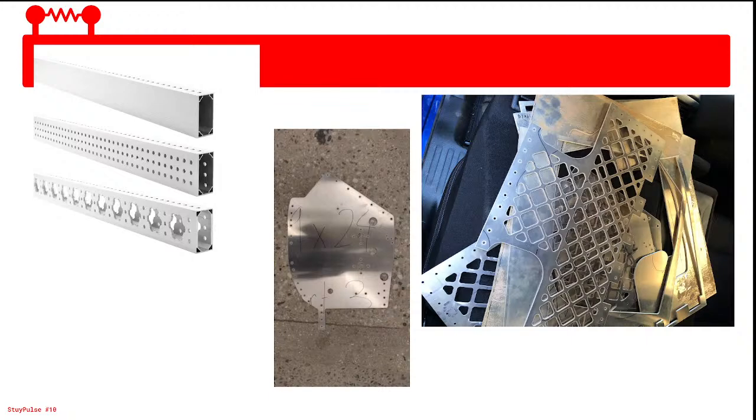But if you look over here, you'll see really thin pieces of aluminum. That's when it started breaking because we didn't leave enough clearance between the pocketing and the edges. So the plate just started breaking off when we were trying to cut it because it was so thin.